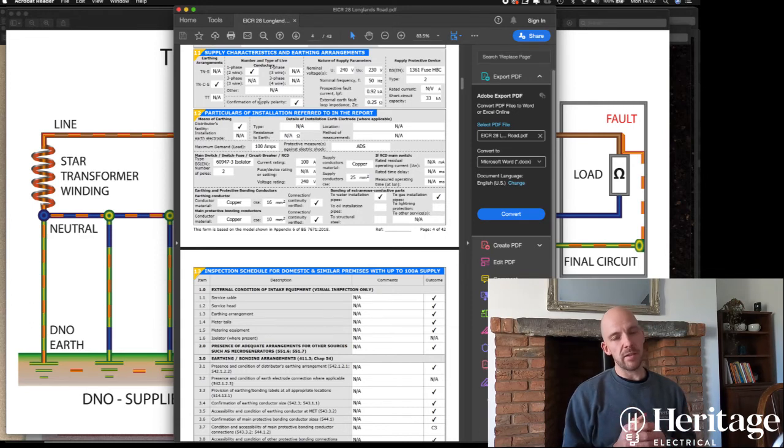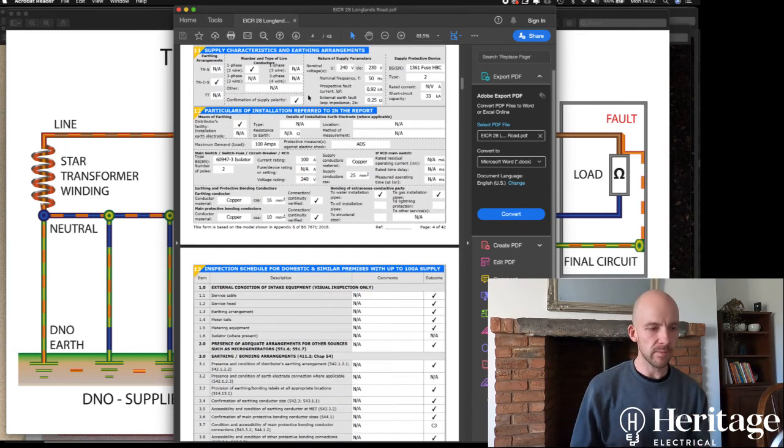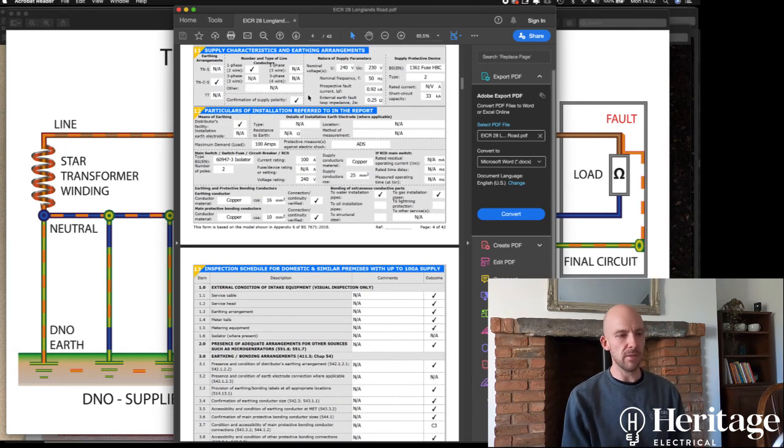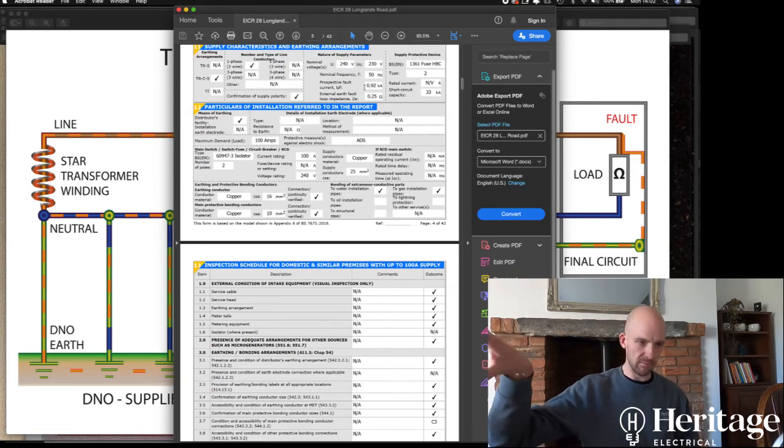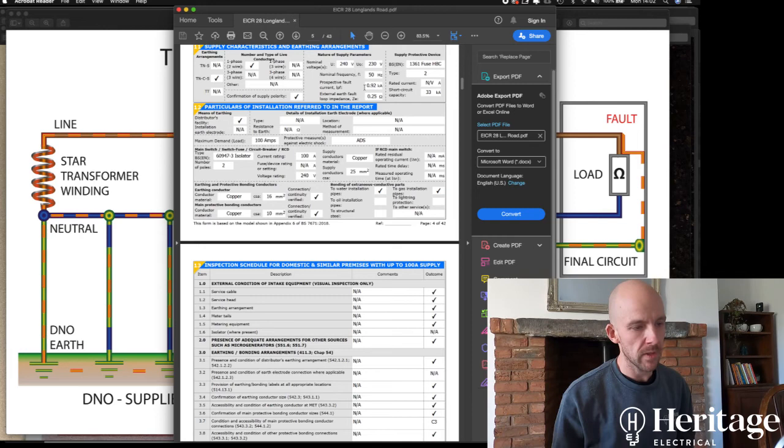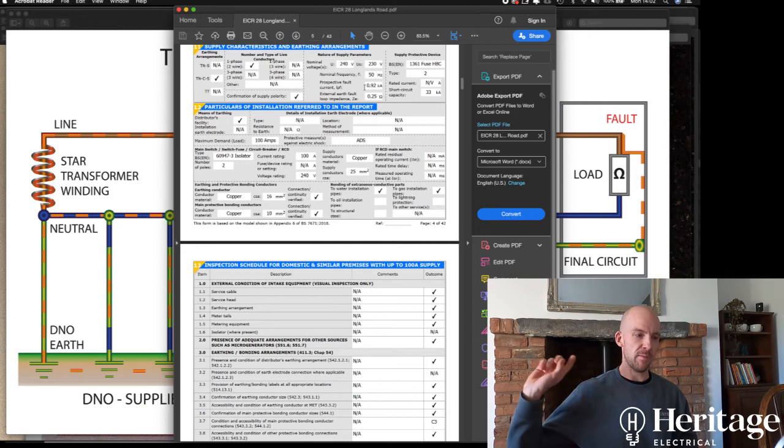More often than not, like I said, this video is about a domestic electrical installation condition report. It's going to be single phase. If you've got a factory or a commercial premises, something like that, it'll probably be 3-phase, which brings more power into the building. We've got the voltage of the supply. Again, this is usually going to be 230 volts. We take other measurements such as the fault current, where your consumer unit is, and what we call the earth fault loop impedance, which is essentially a resistance measurement back to the transformer in the street.